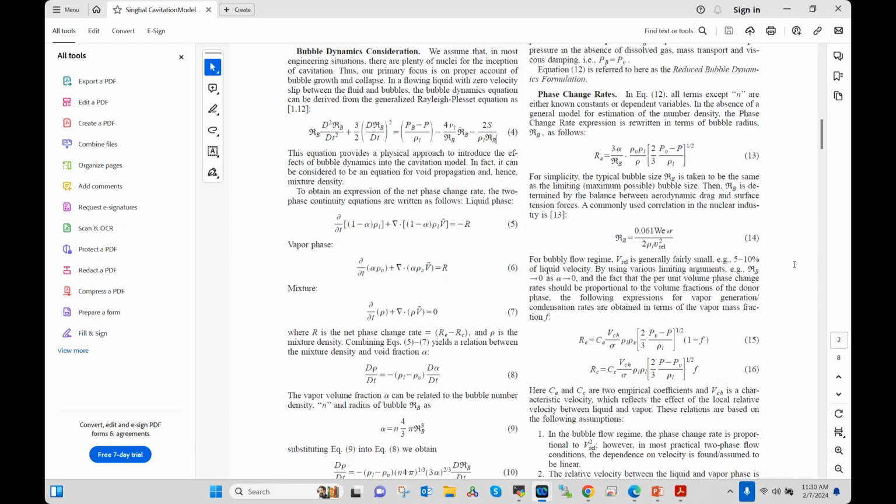It's not absolute. So that means we are comparing our convergence to the initial delta E that we created when we started the first iteration of the first time step. So when we talk about 1 order, that means that delta E term, compared to how it is currently versus the first time, we are comparing that ratio. So if that drops by 1 order, that means that ratio has gone 10 times lower. So that's essentially how our convergence criteria works. I'm saying you do 3 orders for the steady state for the centrifugal pump, or 1 order for the transient